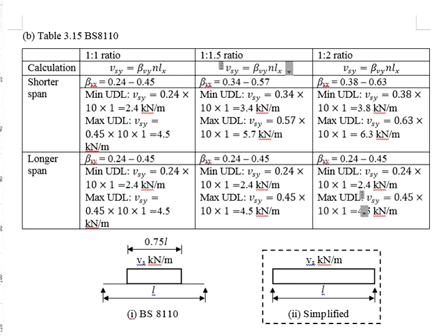Now it depends on you. You may choose to follow strictly the concept of the British Standard, or if you are doing the manual calculations, assuming the same uniformly distributed load throughout the entire span will be easier for you to analyze the shear and moment. Only that you will anticipate slightly bigger moment and shear loads.